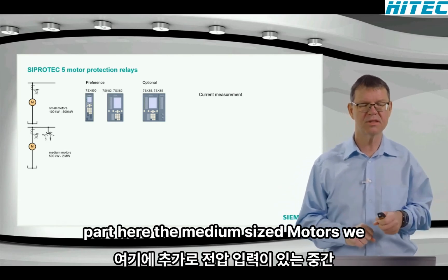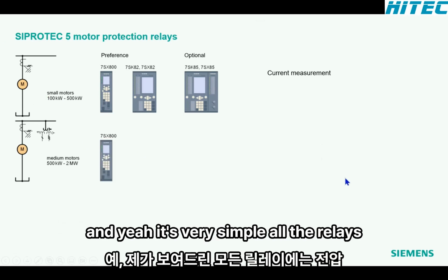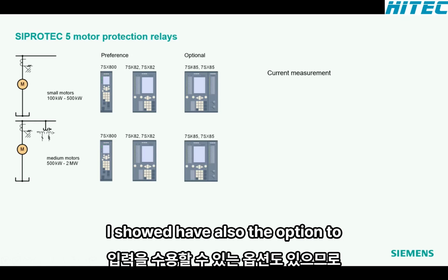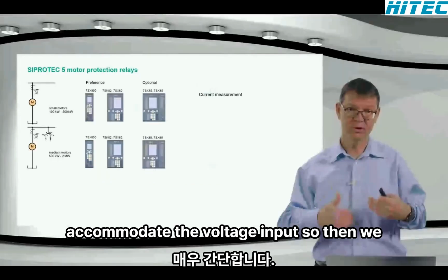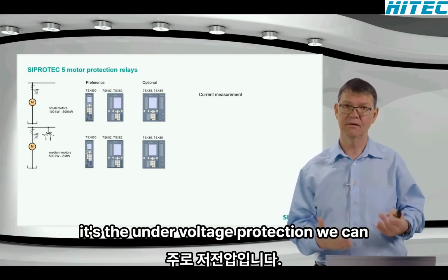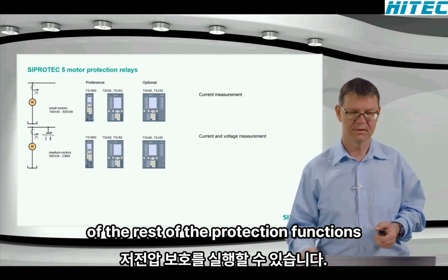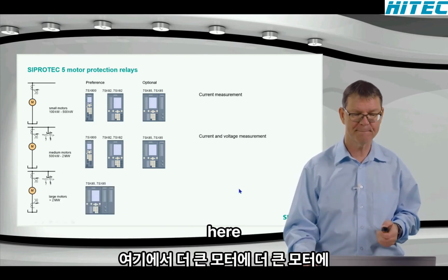Then for the medium part here, the medium-sized motors, we have here additionally a voltage input. And yeah, it's very simple. All the relays I showed have also the option to accommodate a voltage input. So then we can, here for the motor protection, mainly it's the undervoltage protection. We can run the undervoltage protection on top of the rest of the protection functions here.